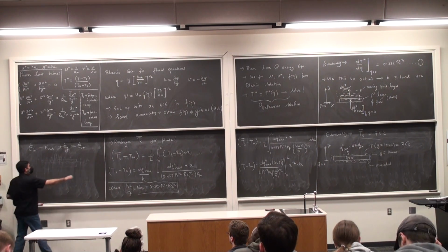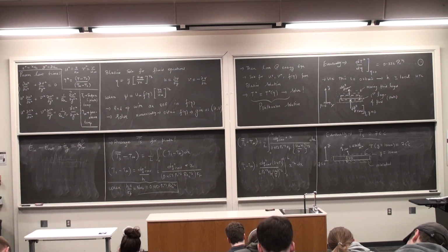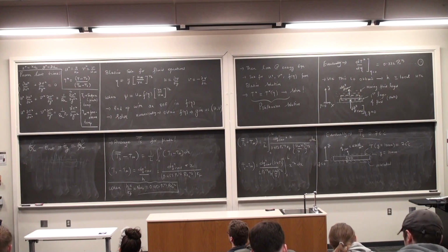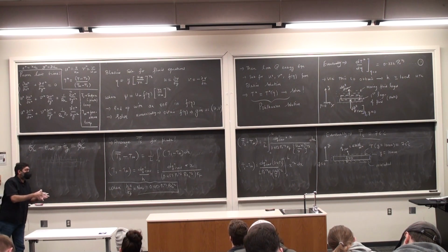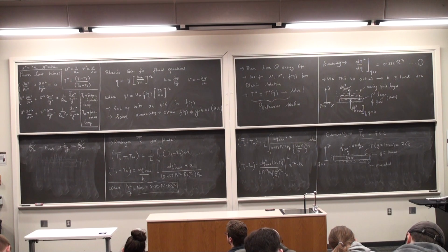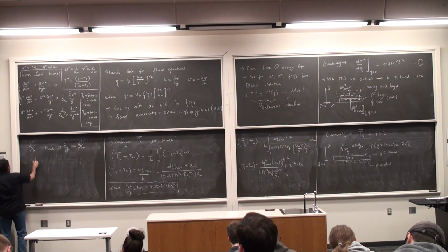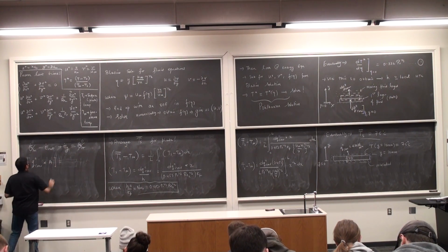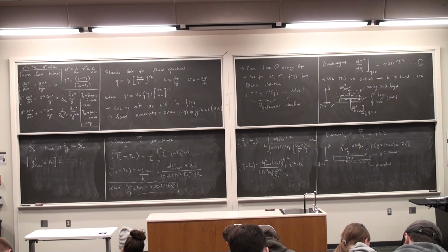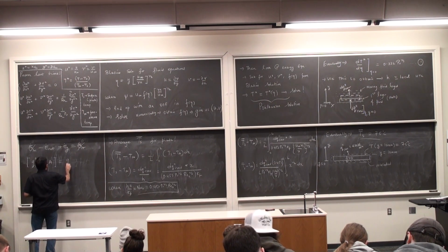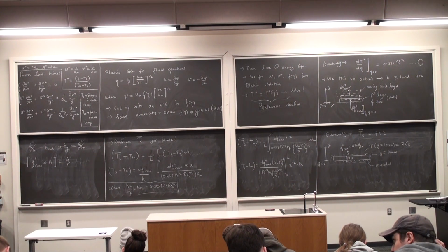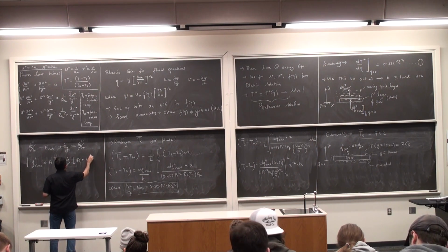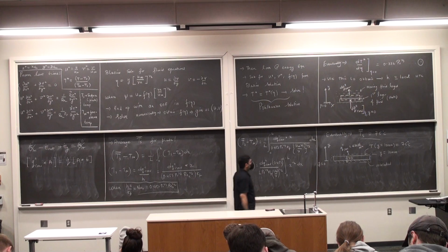E dot stored is 0. Steady state. There is no E dot in in this problem. E dot out is the convective heat flux multiplied by the surface area. So this is Q double prime convection multiplied by the area. This is equal to E dot G, which is Q dot times the volume, which is the surface area times the thickness. Where T is the thickness.